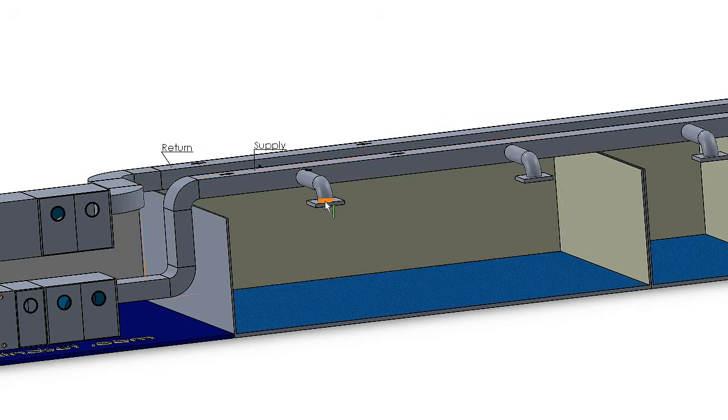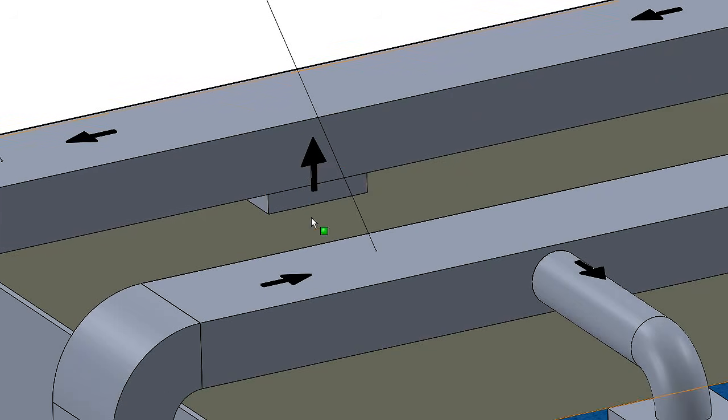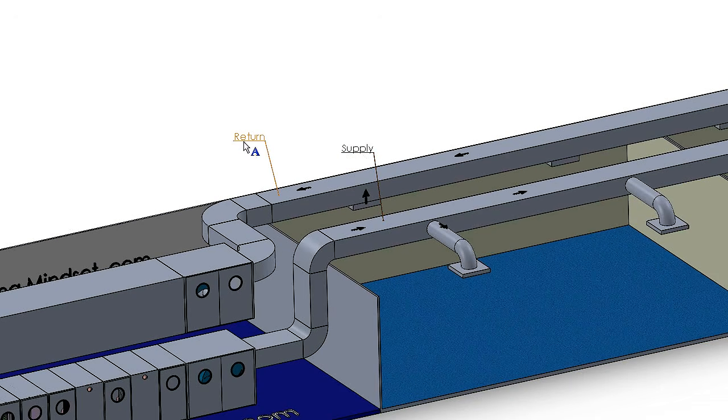So you've got to maintain certain conditions, which will be agreed on in the lease of the contract as well, and also the level of fresh air in there as well. So there will be sensors in this room measuring the amount of CO2, the temperature, etc. And then over the back here we've got another grill, and this is going to the return ductwork. You can see I've also labeled them here, supply and return.